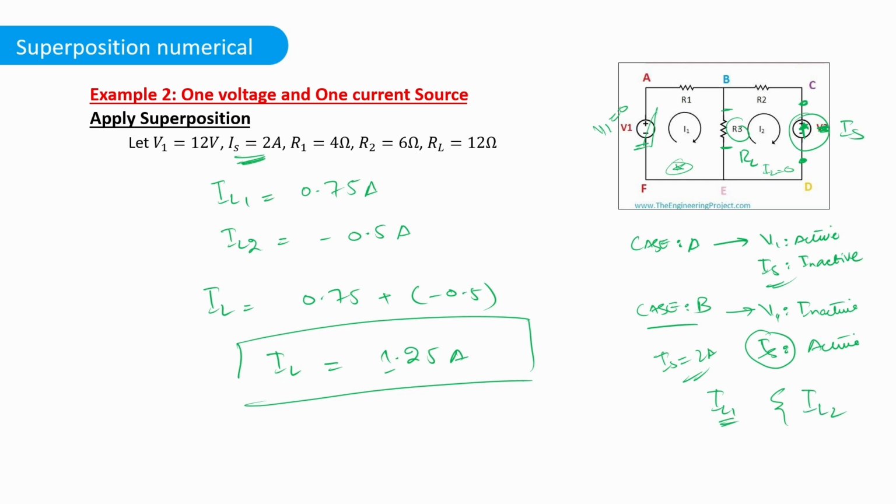So I load 1 is actually the subtraction of both currents. Same goes for this one. The reason is, if we look at this loop, I1 is entering from the top if we follow the clockwise convention, and I2 is entering from the bottom. So this would be the subtraction. You may have a case with a circuit like this, in which one resistor is shared in multiple meshes, so this equation will change. You only have to look at the direction of the currents in that component. Since it is opposite in this example, this will be subtracted.